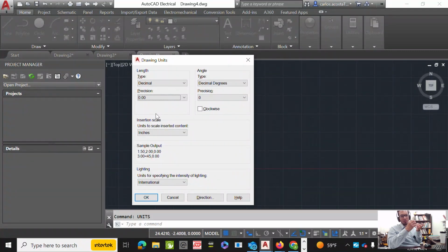You need to have fine, solid connections, closed connections in squares, polylines, so that later on you can extrude them if you're going to do a 3D part. So that is important. Alright, let's just do digits of precision for now, and then I'm going to say okay.